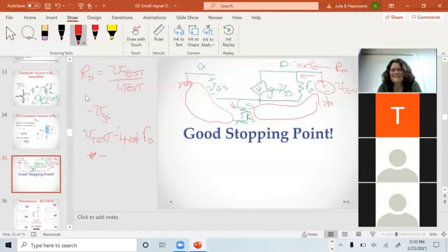Back to the feedback resistance, the reason it acts as such is because the VG needs to stay constant and the source is just tied to ground. So anytime it's changing current, the resistor has to kind of react. It takes a little bit off the output to do that, and it stabilizes everything. It decreases the gain, but it increases the stability.